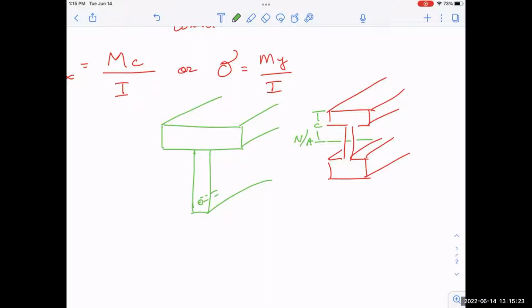So there's these things called post-tension beams, where they pour concrete beams like this, and they put a sleeve of PVC through it, and then they run a cable through it with threads on the end, and they tighten it up. It literally takes the I-beam, like for a bridge out there, and they'll tighten it so it'll actually lift it up in the air and put camber to it, which is what they do for even trailer loads for trucks.